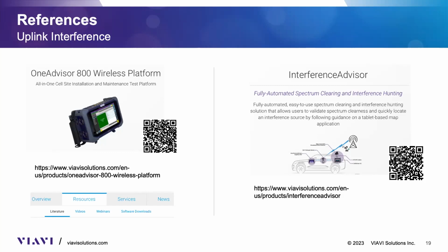All right. For example, if we're doing interference something in 700 megahertz, we can set our Wi-Fi to 1900. Correct. Okay, so the comment is absolutely correct. If you are going to use Wi-Fi in our tablet edition, we highly recommend you band lock the phone to a different block band. If you're hunting band 13 or band 17 or band 12 or band 14, I guess, in the 700 block, you would want your phone locked to AWS or PCS, or the 600 if you're using that carrier, to keep your uplink out of the uplink you're interfering for. Yes, absolutely. Great comment.